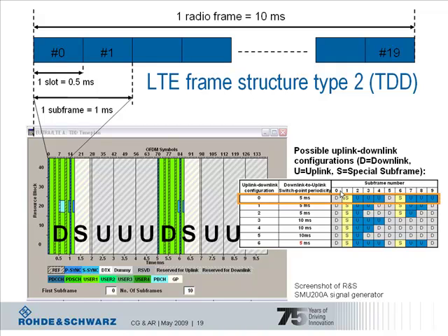So let's have a closer look at one example. Let's have a look at the uplink downlink configuration 0, which is also shown in the screenshot again. So we have represented in the screenshot the 10 subframes, and so subframe 0 would be a downlink one according to the table. So this is a downlink signal, and the green part is actually showing that there is user data in downlink carried in there. And again, subframe 5 is carrying downlink data again. Then we have special subframes in subframe 1 and 6.